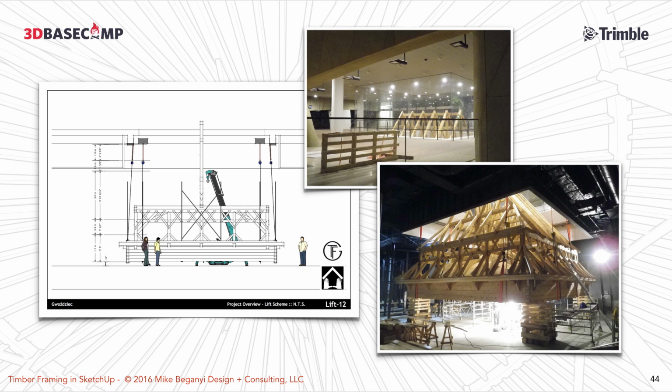So I did a little cartoon as a series of PDFs. It was kind of a stop motion animation where the crane came in, because it had to fit through doors. So it came in, it unfolded itself. I made sure that the thing could pin itself up. This is a still from that. And then I added dimensions for the crew. You could see the red slings in there, and then the chain hoists, and then the cribbing. I have another shot where the cribbing is all lifted up. So this is actually hanging in Warsaw right now.